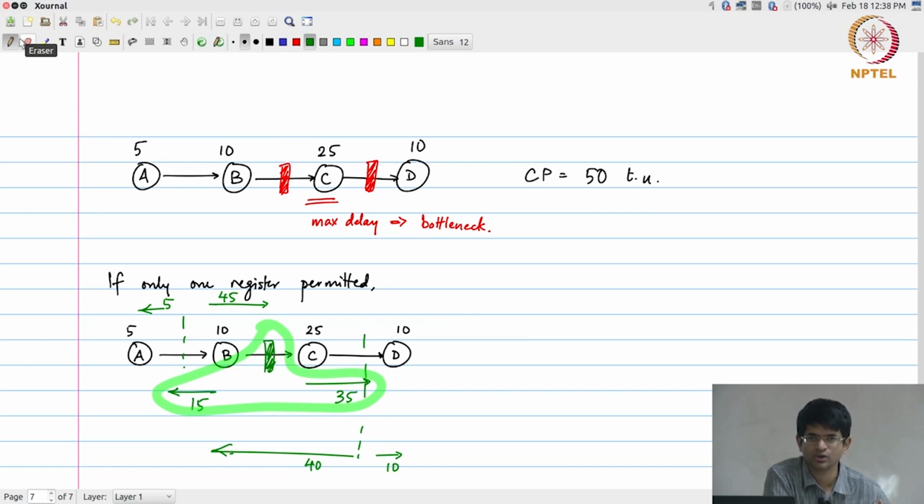So once I have got down to the point where my critical path itself is of a similar order to the clock to Q or setup delays of a register, you are not really going to get any further improvements by pipelining.